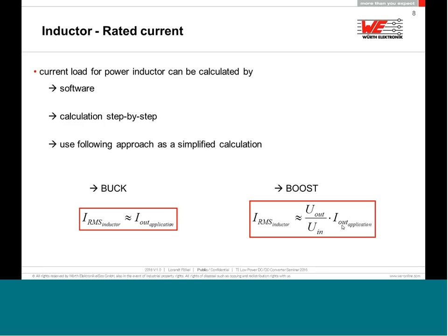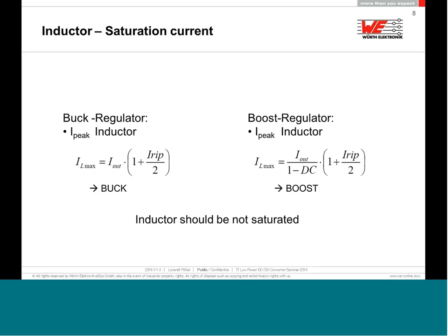The best thing is to have a good efficiency, more like 90%. You will see that your inductor will not run hot, and if you already have 90% efficiency, it will very rarely happen that you also have an EMI problem.